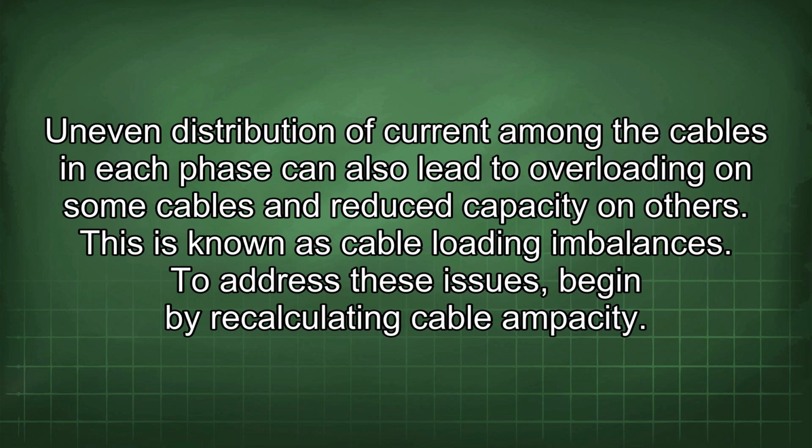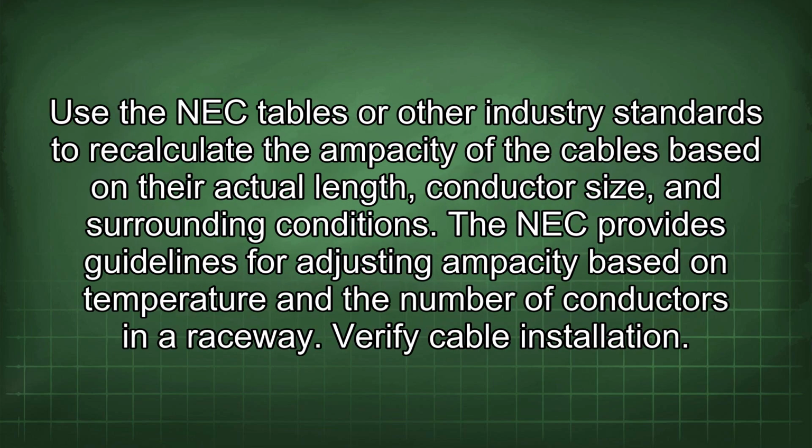To address these issues, begin by recalculating cable ampacity. Use the NEC tables or other industry standards to recalculate the ampacity of the cables based on their actual length, conductor size, and surrounding conditions. The NEC provides guidelines for adjusting ampacity based on temperature and the number of conductors in a raceway.